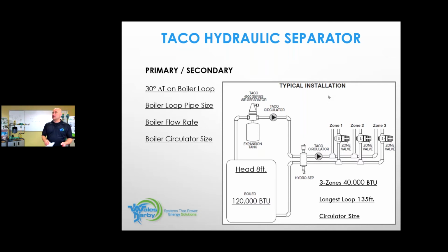So the universal hydronic formula is always a good go-to. Start to figure it out with that, and then let the problem start to come to you a little bit. A couple of answers coming in. Okay, Jim's getting some answers in. What portion are you getting answers in on? A couple on pipe size, 1 inch or 1.25 inches.